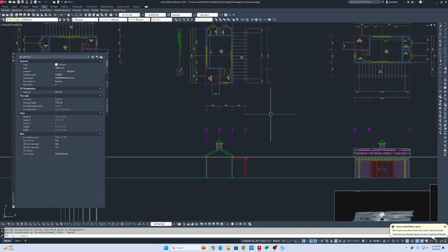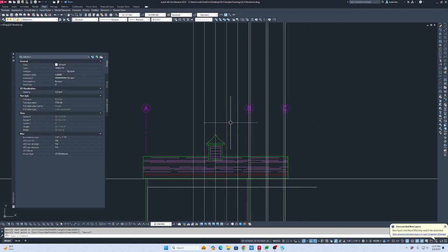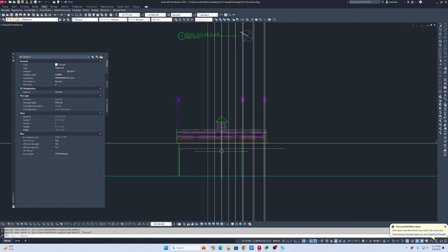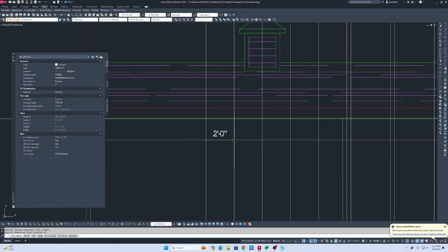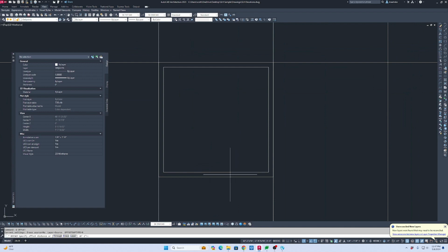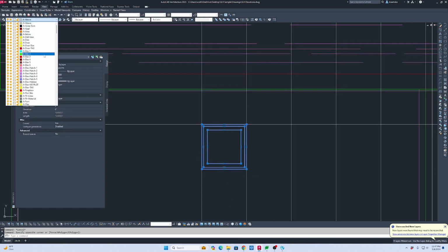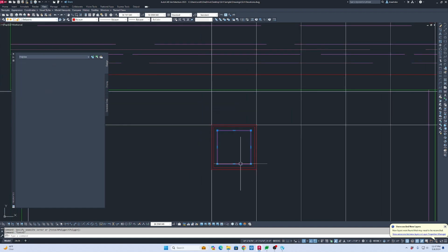So what am I doing over here again? Oops, this one. Got a window. So our window is going to be at 8 feet, I presume. Same head height as our doors. And we got 4 windows. So how big are these? Let's make them square. So 24 by 24. And I usually offset 1 inch for windows for a jamb. And then a sash is 2 inches. Whoops. So these are going to be on the 3rd layer. And I make those the 4th for hierarchy.